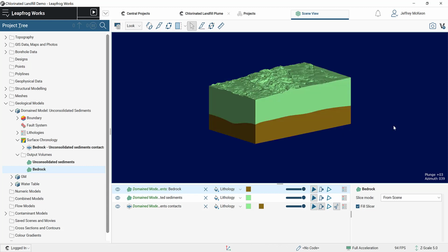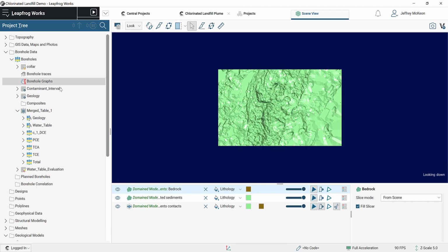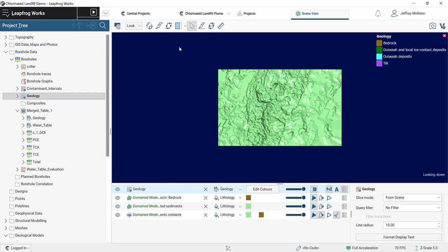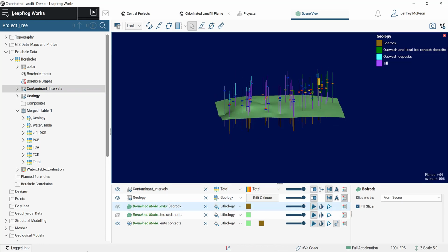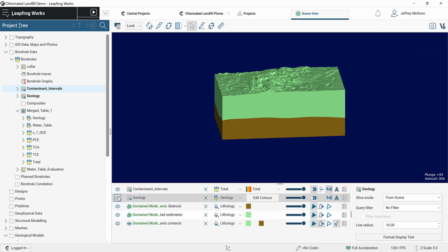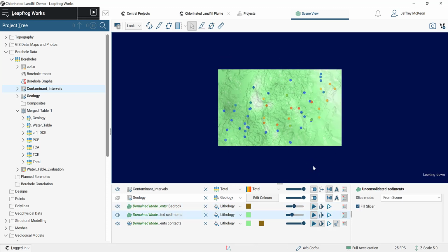Something that's also good to do when you create domains out of your geologic units is to further domain them through a distance buffer. That way, let me just pull in my boreholes. That way, whenever the estimation process is happening, in areas where there is no drilling, it's not going to interpolate too far beyond this and blow out the estimation value.